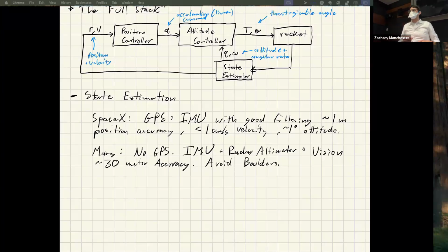So at the end of the day, you're doing filtering over very long periods of time. To first order, say you have range and range rate. That gives you one component of the position and one component of the velocity. To get the full 3D position and velocity, you have to wait for the motion of the spacecraft and the planets to put you in different positions, so that you're measuring a different component of the position and velocity in inertial coordinates. Does that make sense? You measure these things over time, and rely on the dynamics model to propagate those components through time in between.